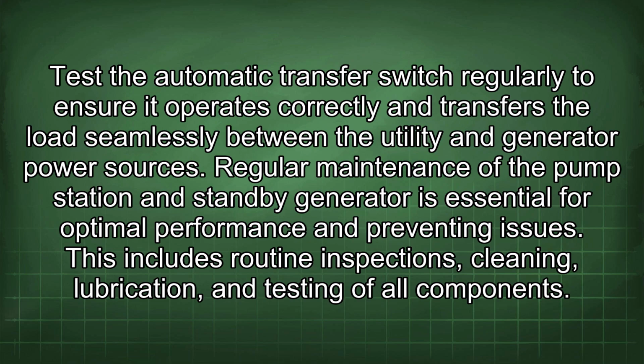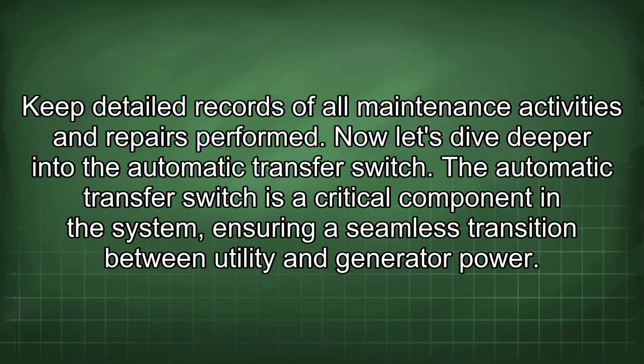Regular maintenance of the pump station and standby generator is essential for optimal performance and preventing issues. This includes routine inspections, cleaning, lubrication, and testing of all components. Keep detailed records of all maintenance activities and repairs performed. Now let's dive deeper into the automatic transfer switch.